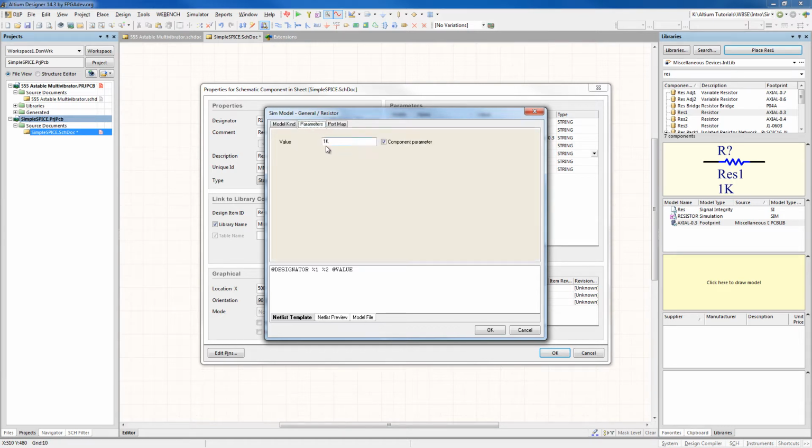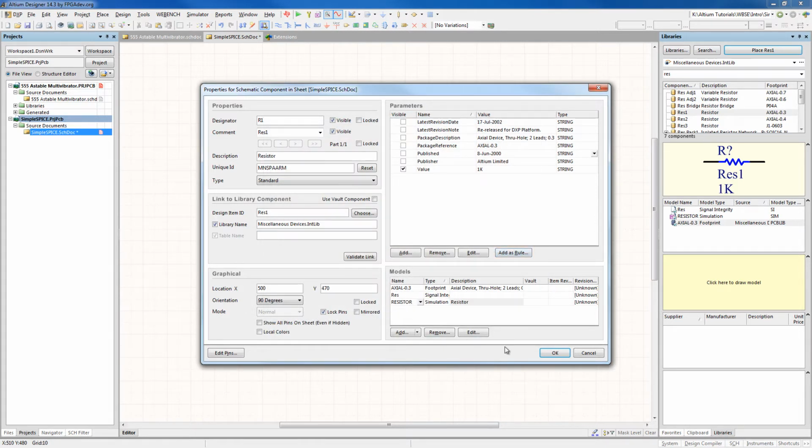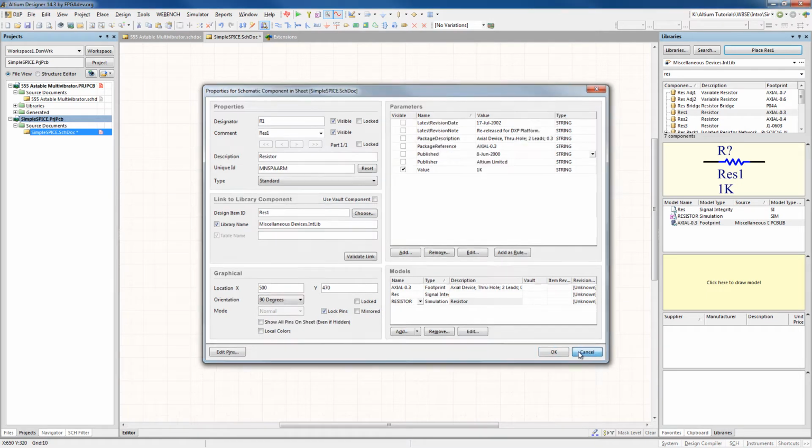There's things that you can add to these additional models, especially if maybe it's a silicon resistor, but really, quite frankly, this is all you really need to do for the SPICE. And so you don't have to bring in any circuit models, you don't have to bring any .mdl models to this. We're keeping it very simple, and Altium handles resistors and capacitors almost automatically just by you saying that you want to use them. So I'm going to press cancel over here because this has already been set up. We'll press cancel over here as well.